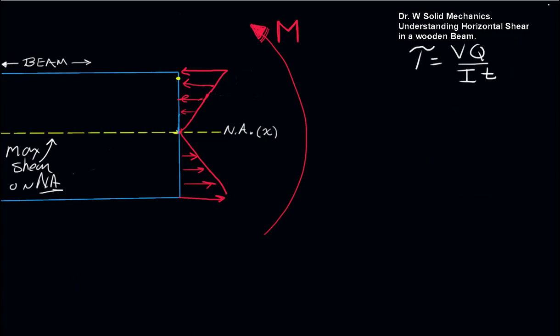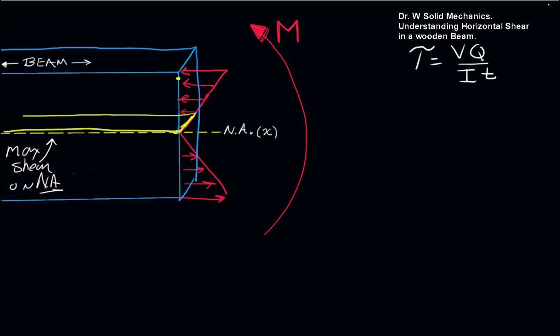If we look again at the beam that's undergoing the bending moment, here's our cross-sectional area that we were just looking at. And here's our beam going back along here. And right here along the neutral axis is our shear plane, which we could show here. So that's the shear plane. And it has a thickness of T here at the cut. And let's call this distance X. And that's the area that these forces out here are acting across.